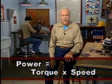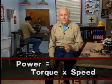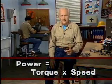Well, so far we've looked at how speed can be changed across a gear set. And we've seen how this change can be described by using a gear ratio. These ratios can be used to help determine the speed of rotation of a gear set if the input or output speed of the gear set is known. Now remember, we said that the reason gears are used in machinery is to transmit power. And the way in which gears transmit power can be described using the equation power equals torque times speed.